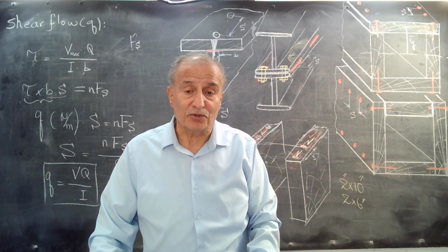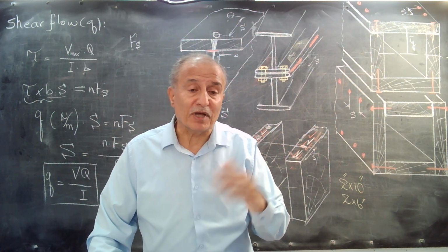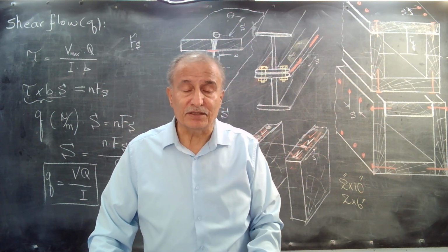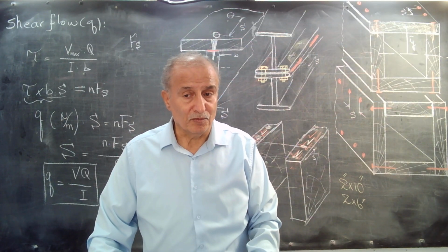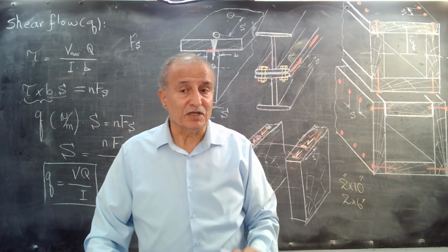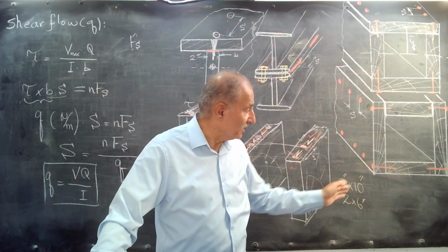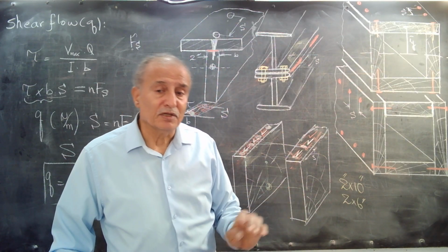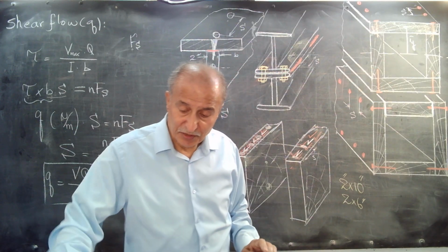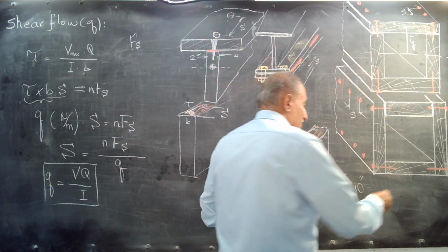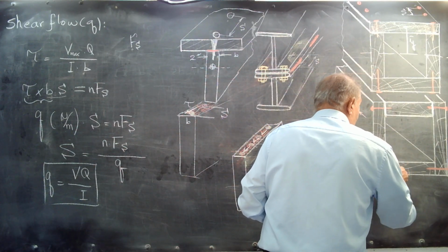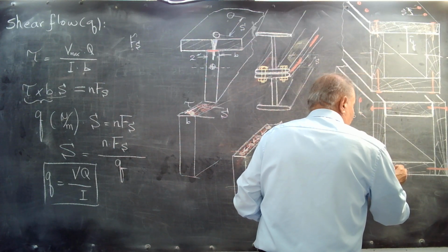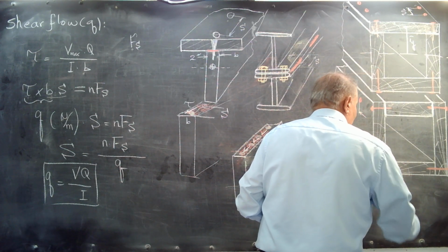Most of them are wood, and we know that wood is an orthotropic material, and the maximum modulus of elasticity is along the grain. In the other directions, it is the weakest, the lowest: one is perpendicular to this, one is the tangential modulus.